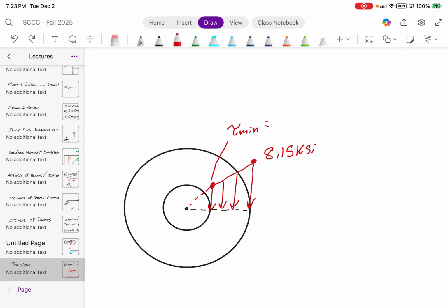It's not 1, but you would basically calculate it using the 12 kip inches times the 0.5 inch radius divided by that J, 1.473, which because of the geometry, you'll just find is 4.07 KSI.